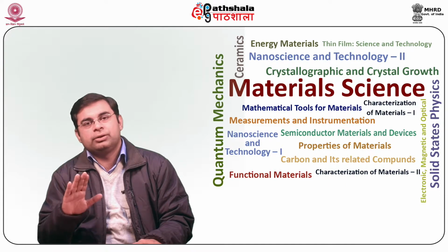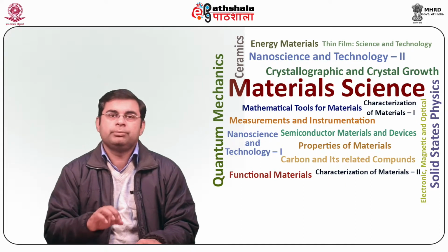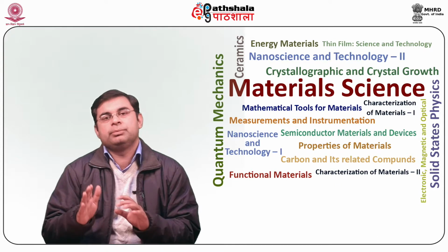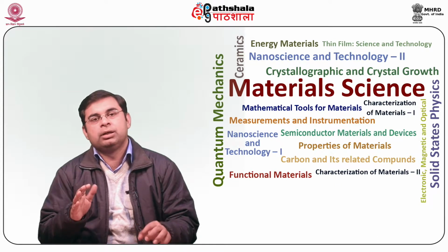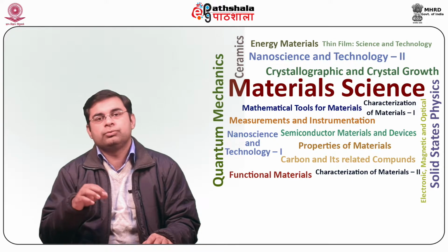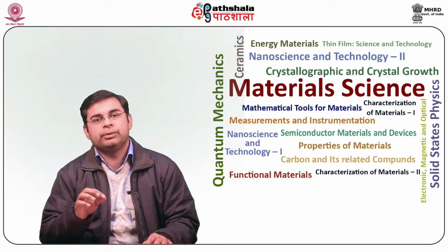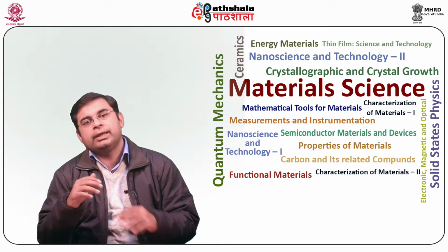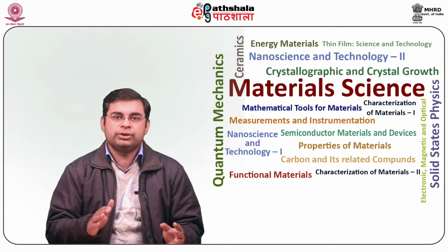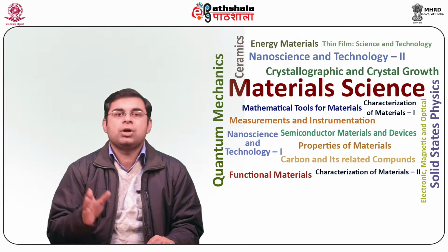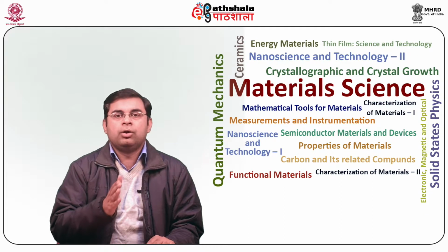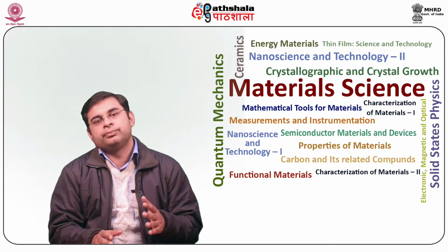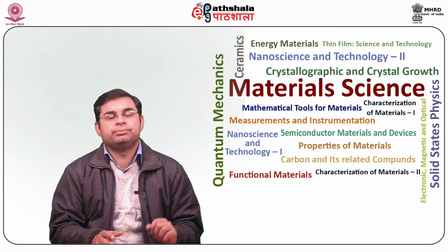Examples of these semiconductors include silicon, germanium, gallium arsenide, etc. Since the valence band in p-type germanium is pinned to the Fermi level of the metal, most metals form ohmic contact with p-type germanium and a Schottky barrier with n-type germanium. This problem can be alleviated by including additional processes, for example, addition of an insulating intermediate layer to unpin the bands. Germanium nitride insulation is usually used in the case of germanium.